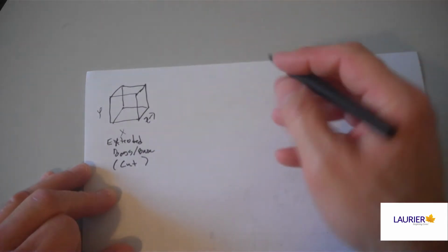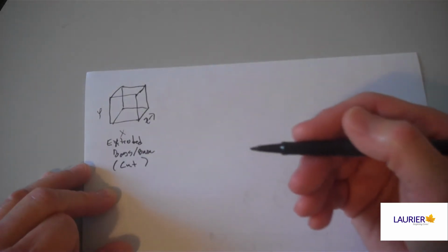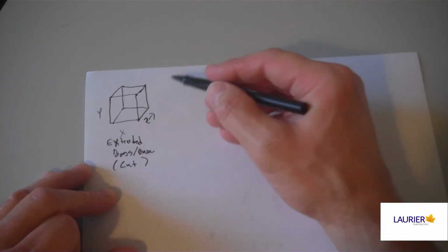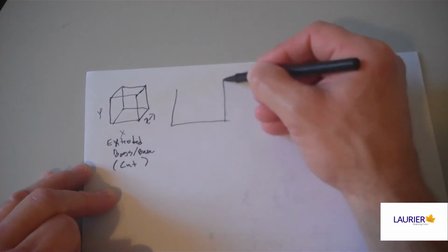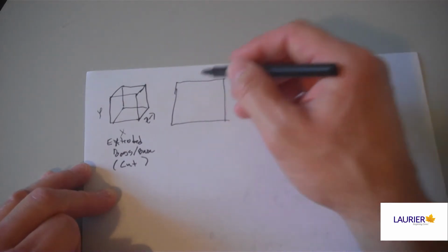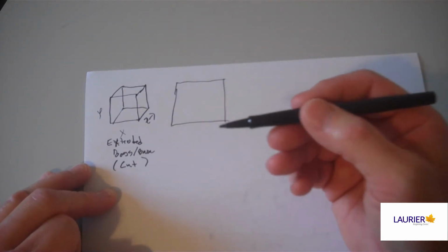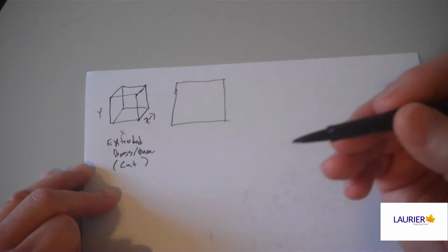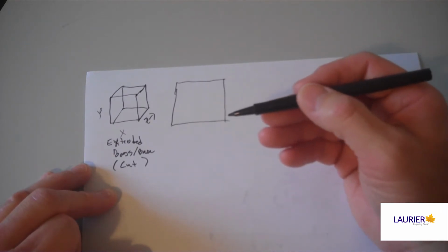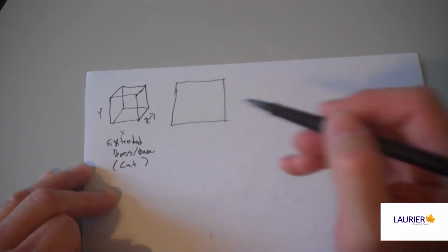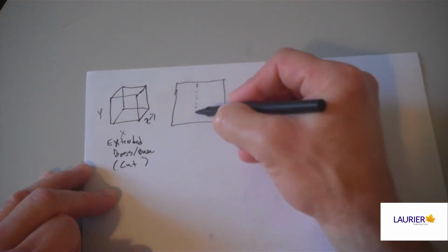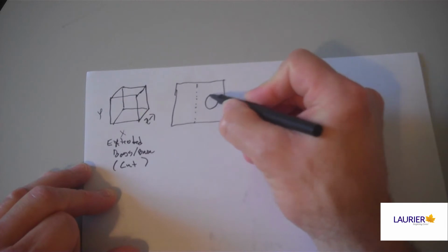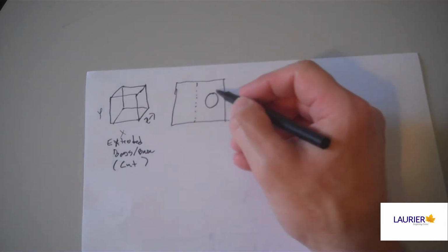The next type of shape we can make in SolidWorks again starts with a sketch drawn on one plane. So we start by picking our plane because the first thing we always have to do is tell the CAD where we want to draw our sketch. For this type of solid, we'll first need to set up a line called an axis, which will act like an axle. Things revolve around axles. Then we'll put a contour off to the side of that axis we've just created. Now we've got our nice shape here, and it captures the area within its contour.